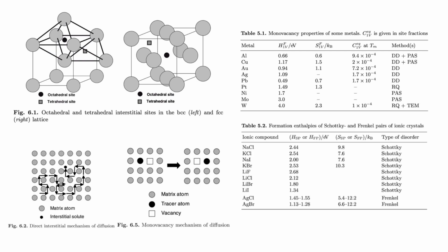So if you look at the phase diagram between iron and carbon, you can see for the ferrite, alpha, or the BCC, carbon has a little bit of solubility in BCC iron, but has a huge amount of solubility in austenite, or gamma phase, or FCC iron, of up to 2.14 weight percent. So you can imagine carbon is going to be more comfortable in the FCC structure.